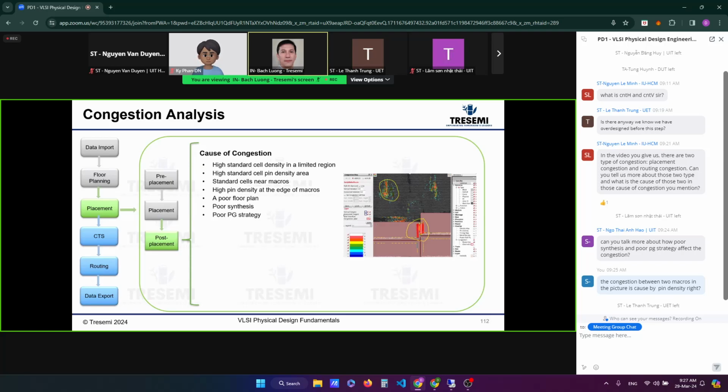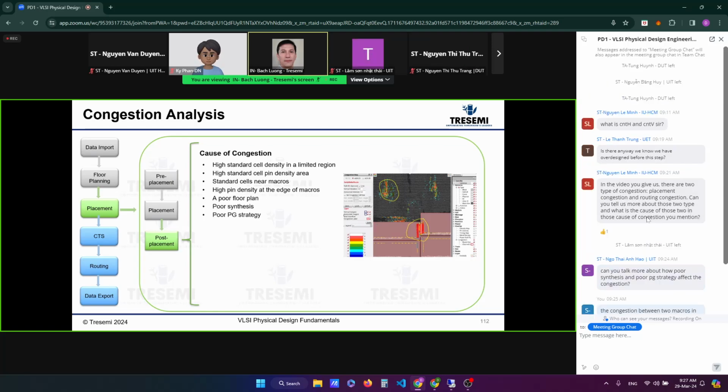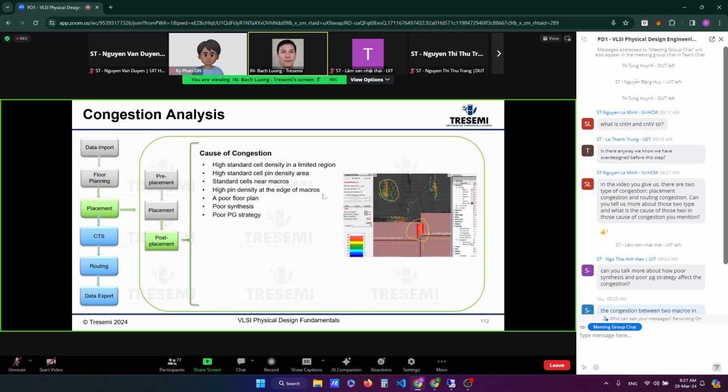So what happens is you go to placement based on that particular size you estimated, 10%, but then your synthesis miss or gap is 30%. Therefore, the tool has to add a bunch more buffers to make up that 20% trying to meet the target. And so you blow up your area. That means your density is too high, and you move cells around. So that's what I refer to as poor synthesis, the gap.